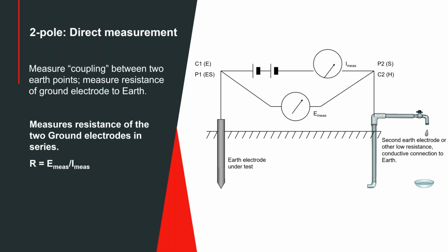And what you see on your display then is a loop resistance of this whole electrical loop, and you're counting on that being mostly the resistance of the earth. And you're counting on your return, such as the water pipe system, as contributing relatively little to the measurement.